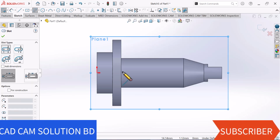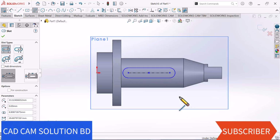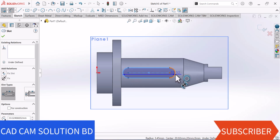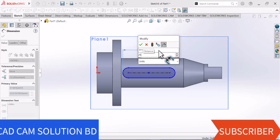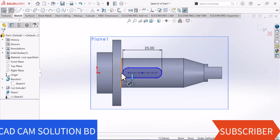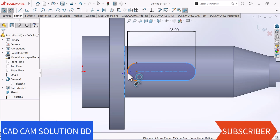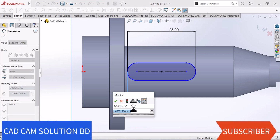Now here select slot. Now select here, shift, this arc and this arc. Give the value here 25. Now this line and shift select this arc. Give the value 6.